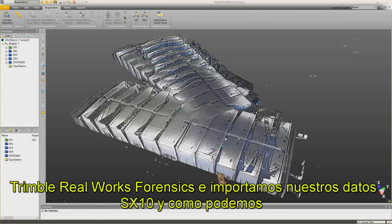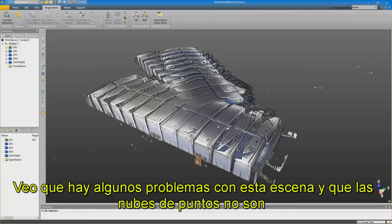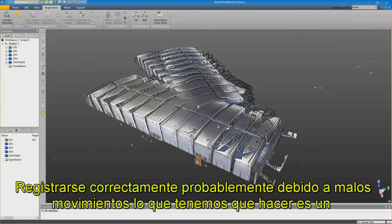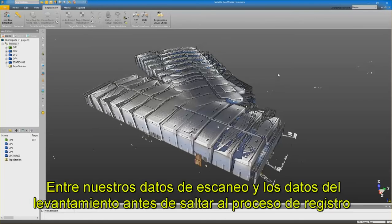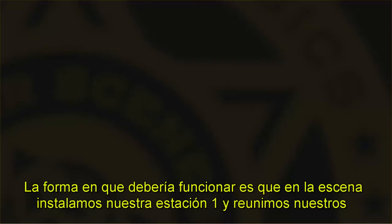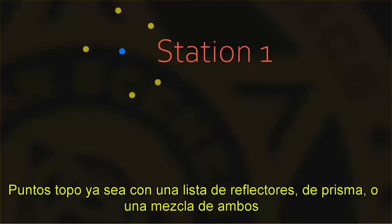So we've moved over to Trimble RealWorks Forensic and we've imported our SX10 data in, and as we can see there are a few problems with this scene, and that the point clouds are not registering properly, most likely due to bad moves. What we need to do is a cloud-to-cloud registration on this. So let's take a look at the relationship between our scan data and survey data before we jump into the registration. The way it should work is that at the scene we set up our station 1 and gather our topo points, either with a prism, reflectorless, or a mixture of both.